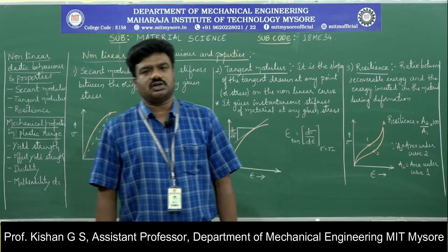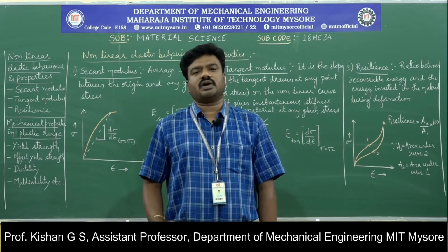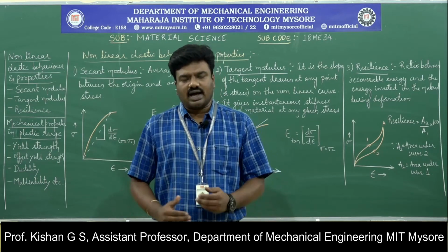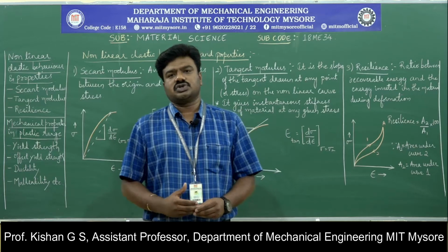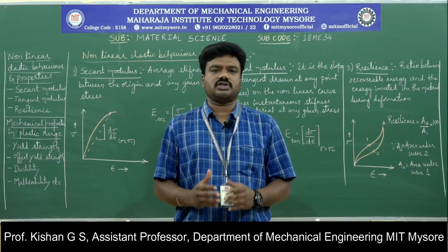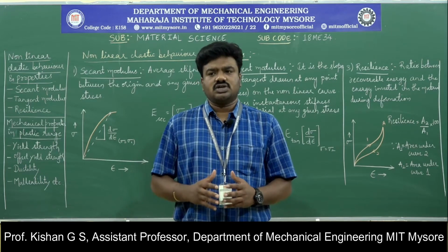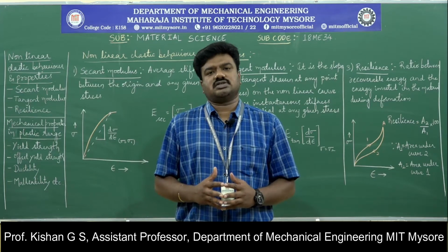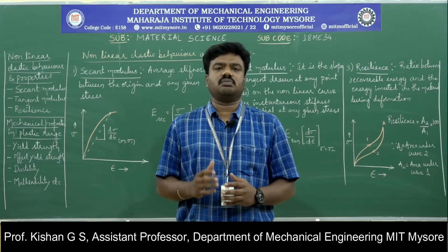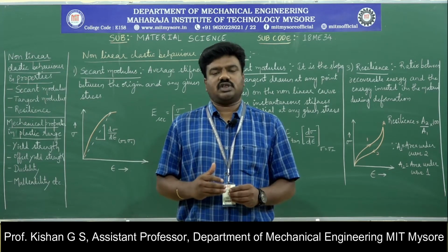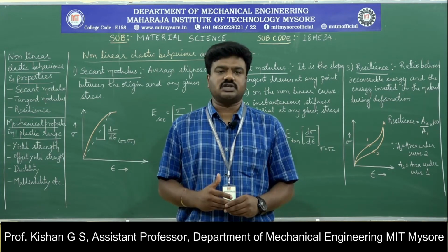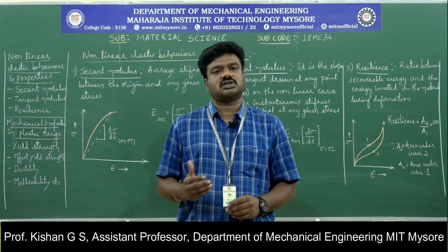So in this particular session, we are going to cover the extended part of mechanical behavior in material science, what has been covered till the last class. To brush up on that content, we know that the mechanical behavior of materials is studied under two regions: one is the elastic region, the other is the plastic region. To be very specific, the elastic region is the range in which the material, upon unloading, comes back to its original condition. If the material is loaded beyond the elastic limit, wherein it cannot come back to its original shape and size, then we say the material lies in its plastic region.